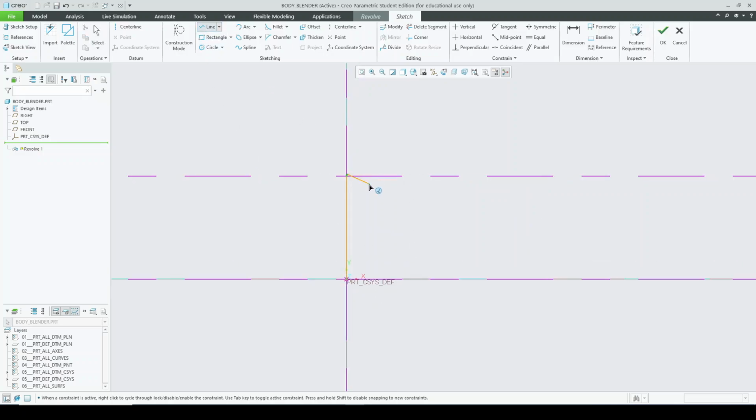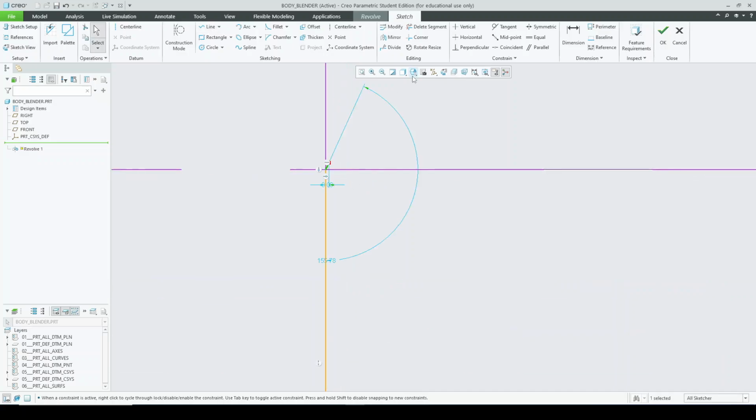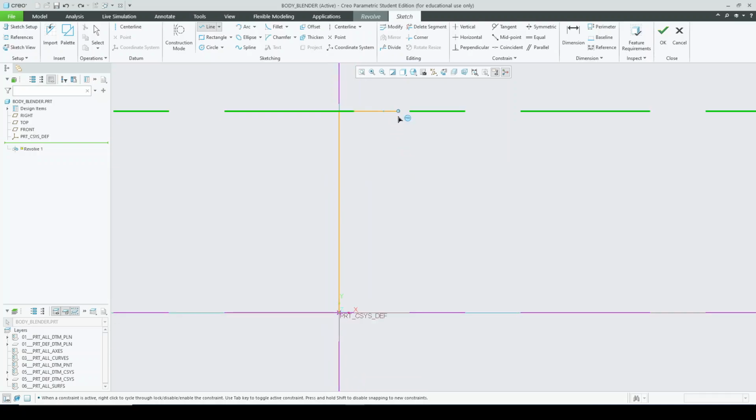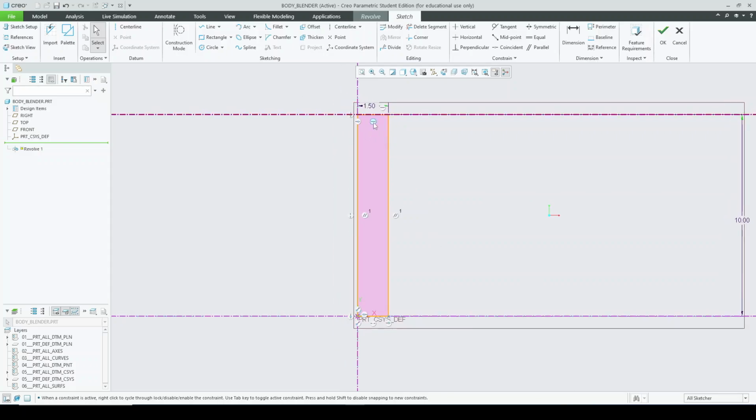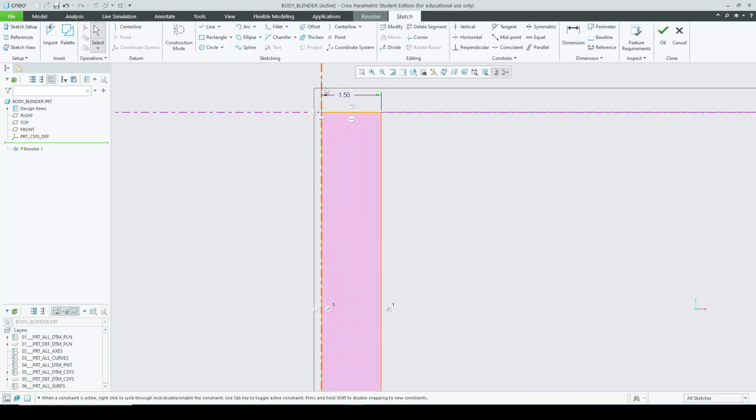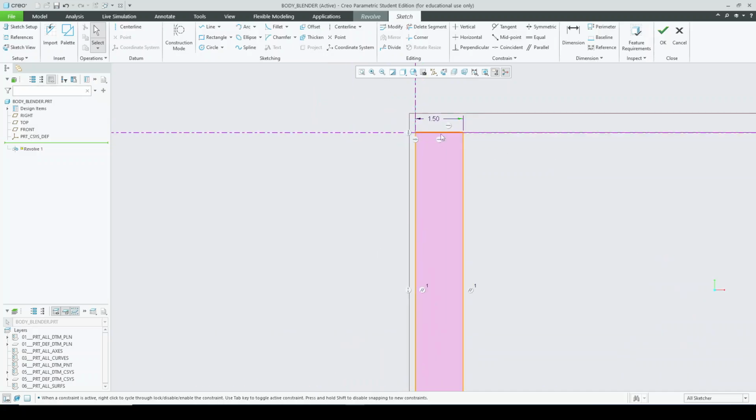Now I'll create one, I'm sorry, Control Z. Yep, I want the diameter to be 3 inches. I'm creating a perfect rectangle at first. So 3 inches divided by 2 is 1.5. Since I'll be revolving it, one half side should be at the right or the left of the center line.